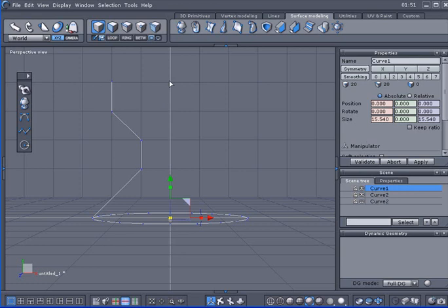Now if we look, and we're going to go to the left here, how many square grids do we have on the left that will meet the halfway mark? We got 1, 2. Now when we use this extrude line, it will mirror it on the other side with equal value. So if I have 2 on the left, it'll do 2 on the right. And the top should land right here. Let's take a look at that.